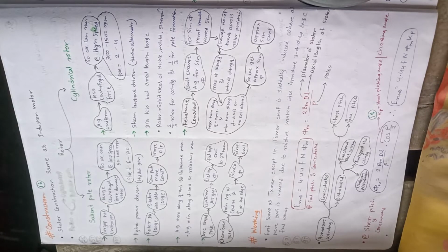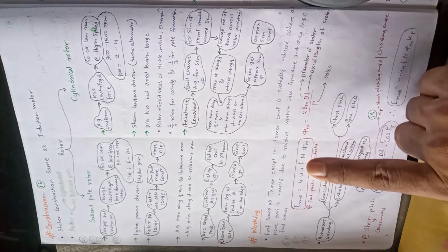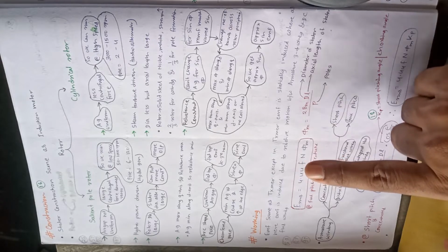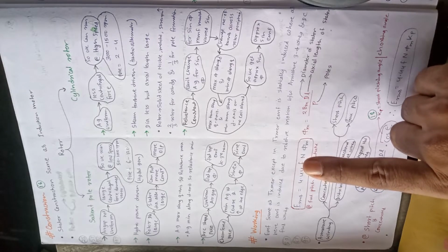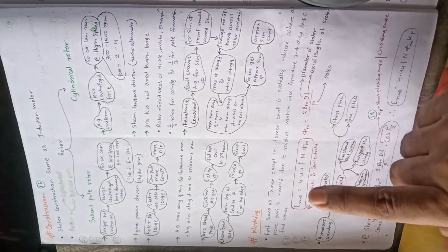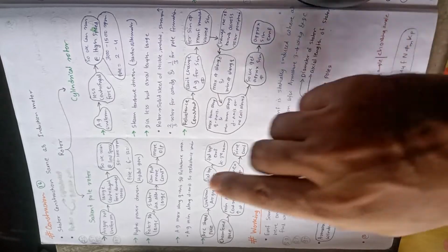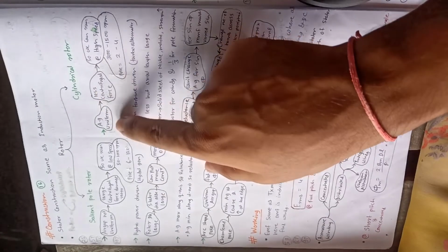In construction we have two main parts, stator and rotor. Stator is the same as the stator of an induction motor, which has three-phase distributed winding that works only on three-phase AC supply. When we talk about rotor, we have two types of rotor. One is salient pole rotor and another is cylindrical rotor.